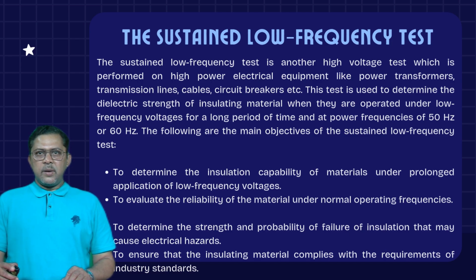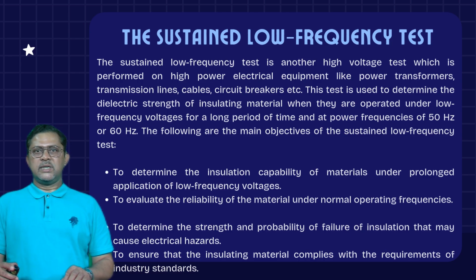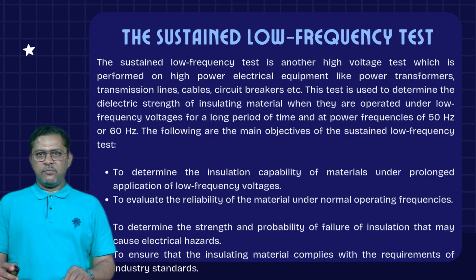The following are the main objectives of the sustained low frequency test: to determine the insulation capability of materials under prolonged application of low frequency voltages, to evaluate the reliability of the material under normal operating frequencies, to determine the strength and the probability of failure of insulation that may cause electrical hazards, and to ensure that the insulating material complies with the requirements of industry standards.